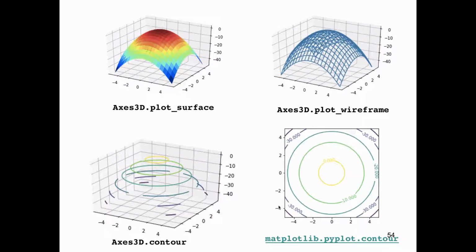So if you want a real strenuous exercise, you pick part of the park that has contour lines bunched up. If they're spread out, then that's an easy walk. Because again, contours are typically plotted at certain spacing. And if the contours next to each other are very close together, that means that I switched to a different height over a short distance. Okay? And all of that is true for reservoirs as well.